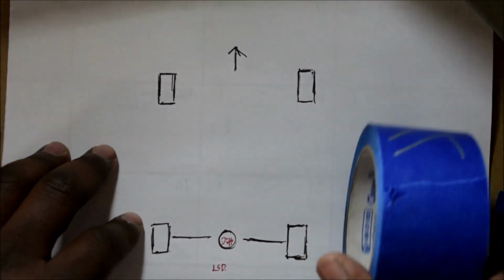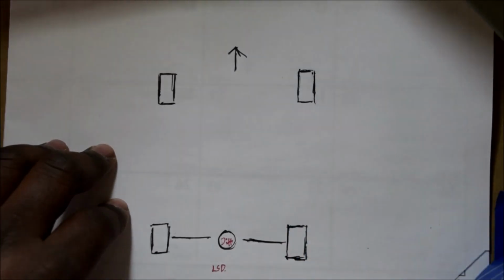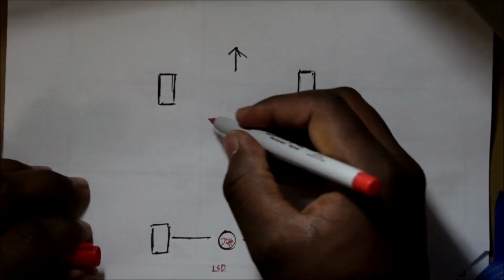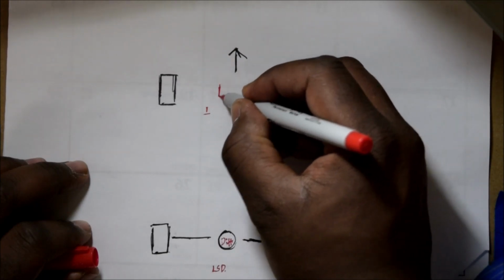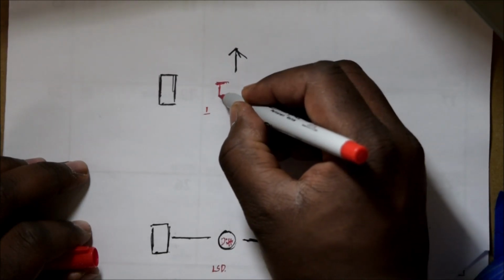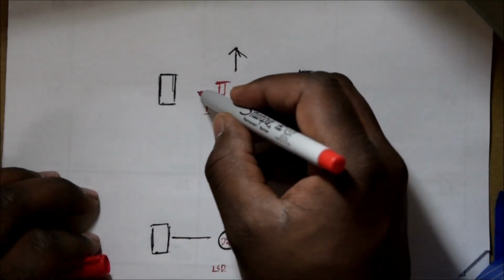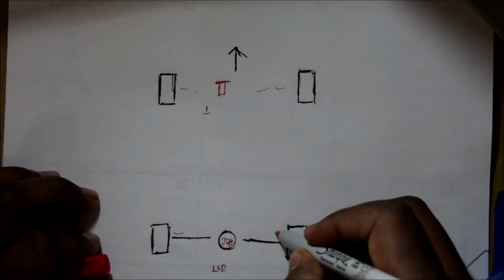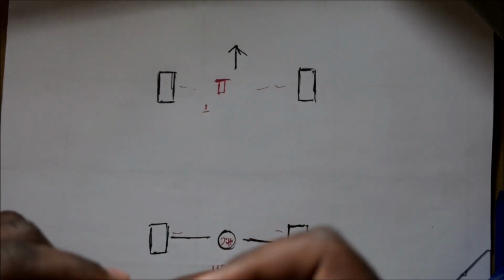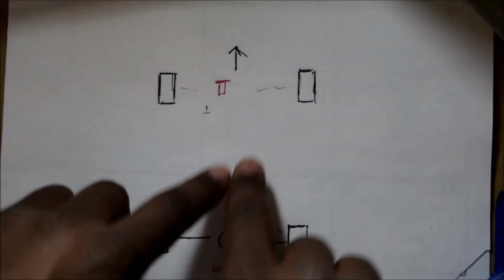So when you hit your brakes, typically what happens is that for your braking system, you have your pedal here. Should I really draw that? Let me skip on to your master cylinder here. This is what keeps your fluid. And somehow, brake fluid has to be sent to each corner, each wheel, or each axle, if your car is braked by the axle. And what happens is fluid is sent to each corner, right?